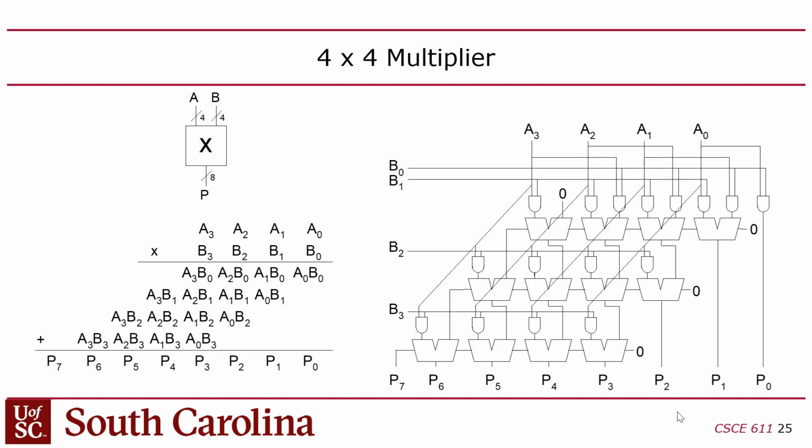So you have A coming in, and then you are adding A to itself with these first levels of adders here, except you've got these AND gates which are controlling whether you're turning on A or not turning on A into that adder level, right?